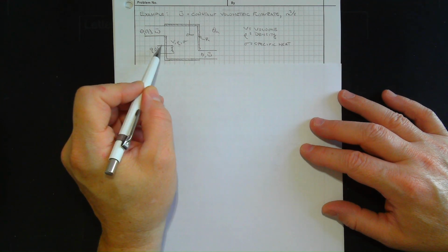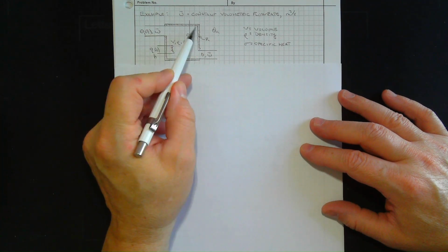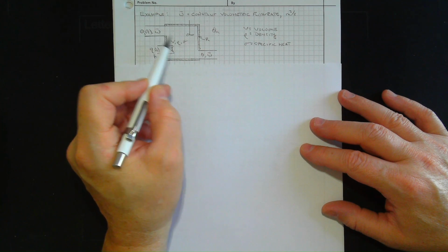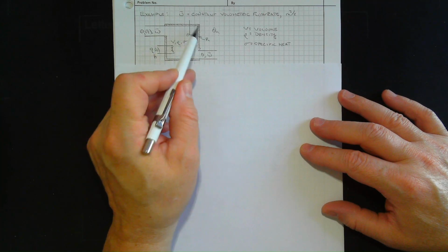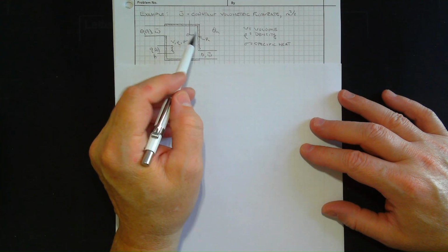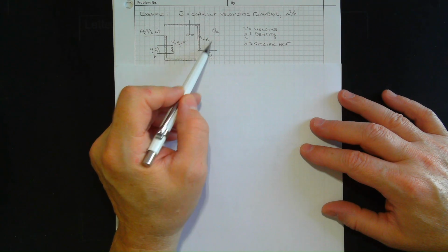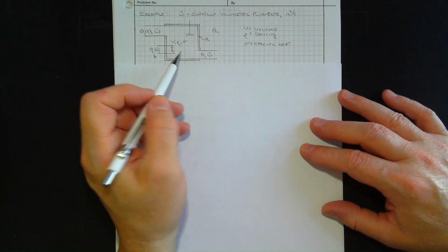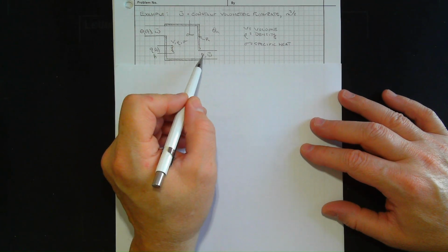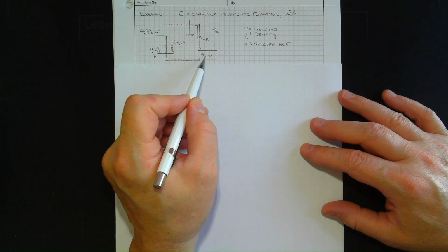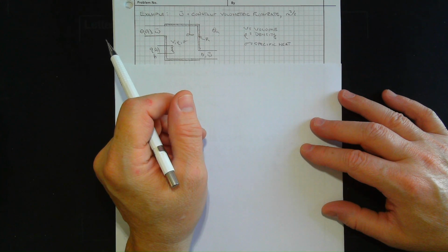We have heat being applied here because we want to heat this thing up. The tank will have a characteristic volume. The fluid will have a characteristic density and specific heat. The walls are insulated, but not perfectly, so there is heat flow out through the walls, and that is regulated by this R value. Then as stuff heats up, it goes outside the back end, with some characteristic temperature and the same flow rate at which the material arrived.